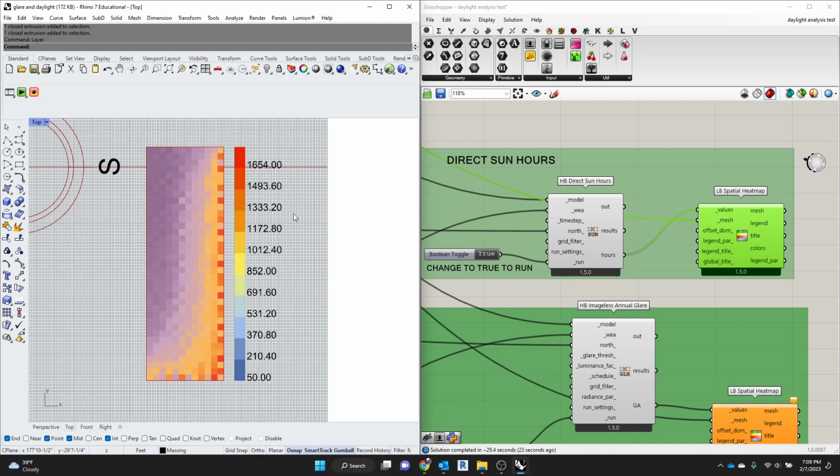It's literally, there are tools that you can get like intensity of light on the facade. This is how much light is actually hitting 3 feet off the ground in the room. But it's not intensity. So it's not like at this point in day it's this many lumens or lux. It is literally, is there a direct path from this point to the sun at every hour of the year, right? So not intensity, literally, is there sun on this spot, and how many hours is there sun on this spot? So what do we think these numbers mean?